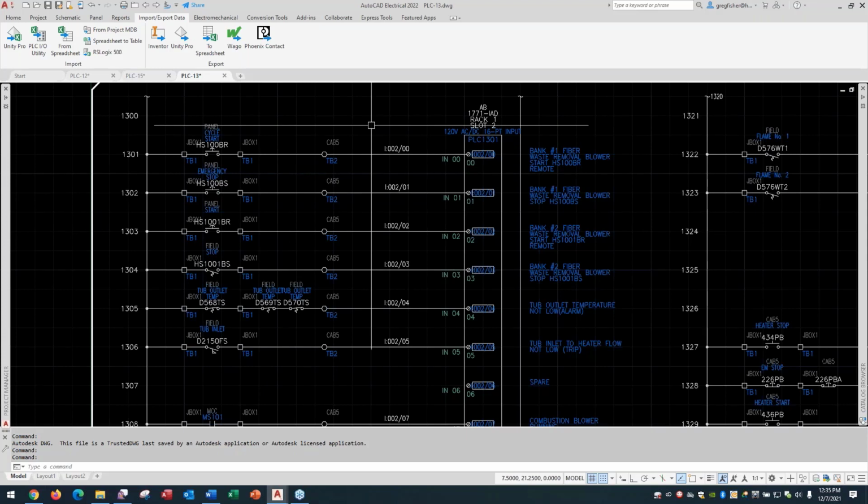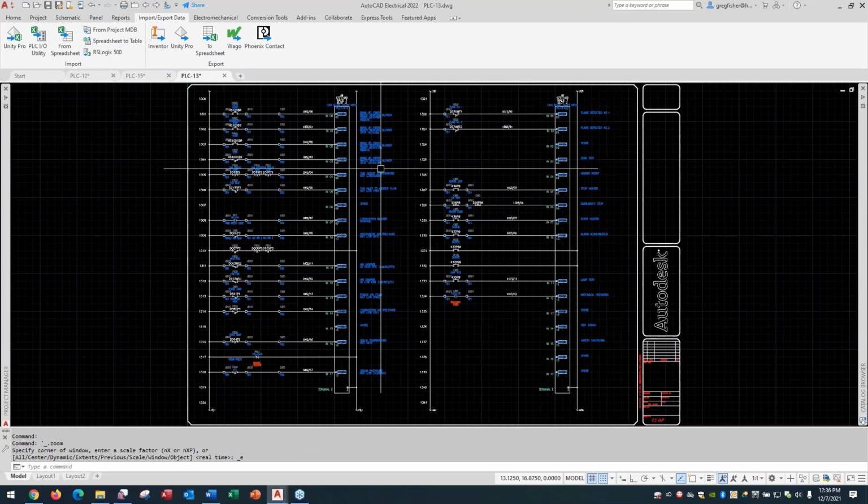So that's the whole point of, okay, and who knows what you might be changing, right? We're just talking concept here. You saw me make some changes to a spreadsheet, save that spreadsheet, run it, and it's going to apply all that information. Well, you might swap out a whole card. You might swap out the PLC module itself, which I'm going to show you right now. So who knows what you're going to be changing, but the whole point is copy the spreadsheet to your new project, make some changes to it, and you're done with your IO, period, end of story.